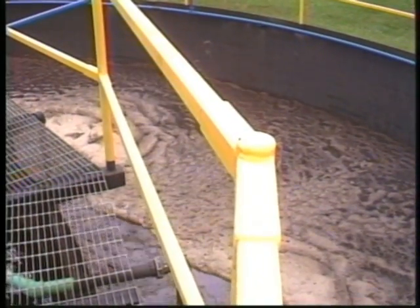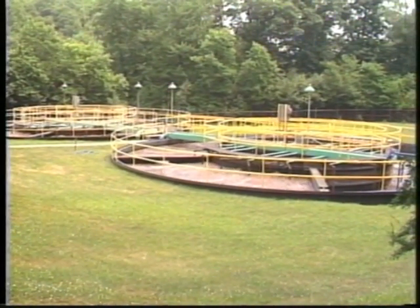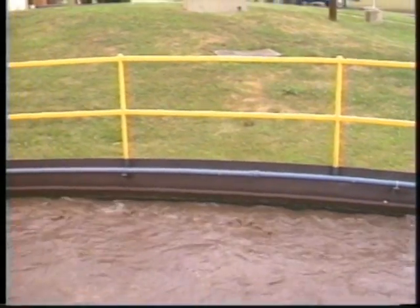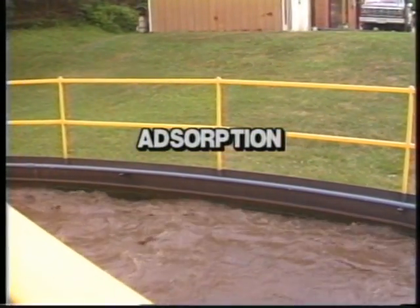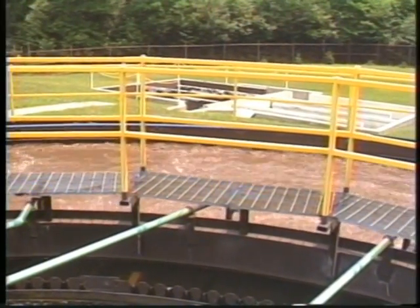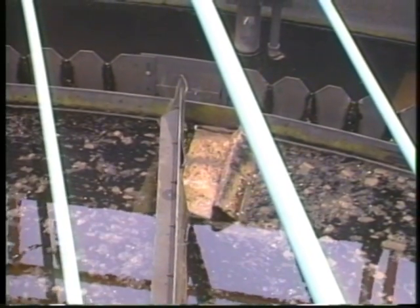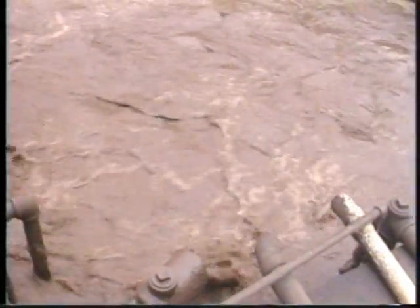The contact stabilization activated sludge process is different from the conventional activated sludge facility and usually utilizes two connected aeration tanks. In the first tank, known as the contact tank, the influent wastewater is introduced to the hungry microorganisms where a process known as adsorption takes place. The wastewater usually spends 30 to 60 minutes in the contact tank where the hungry microorganisms become attached to the food in the wastewater. The wastewater then passes into the clarifier where the microorganisms settle out and are returned or wasted. The return sludge is not returned to the contact tank.